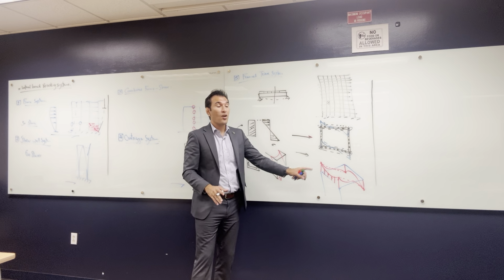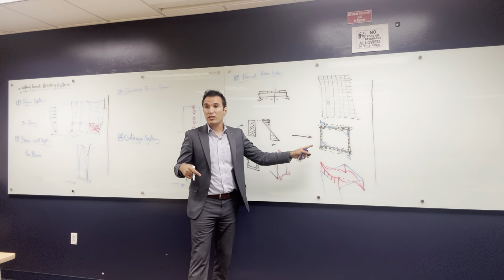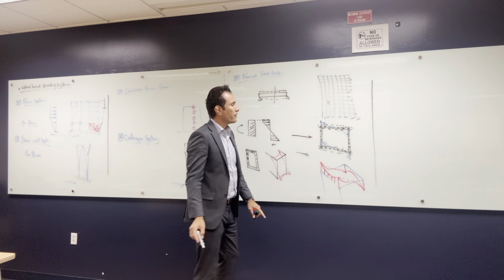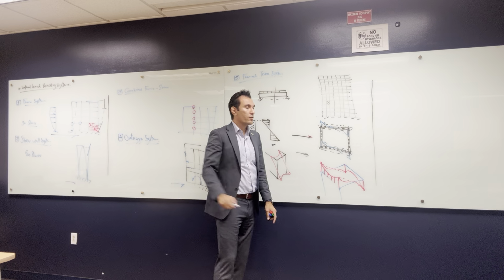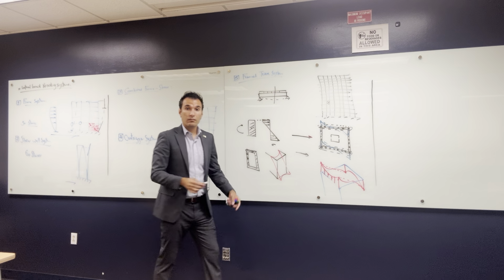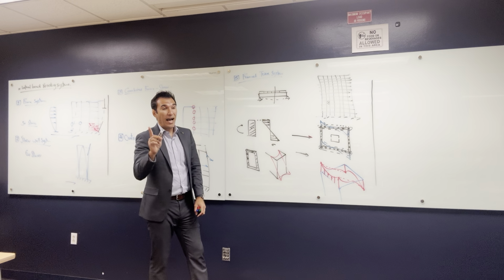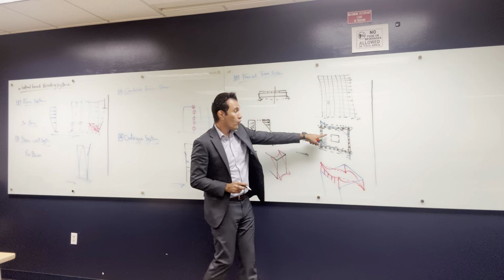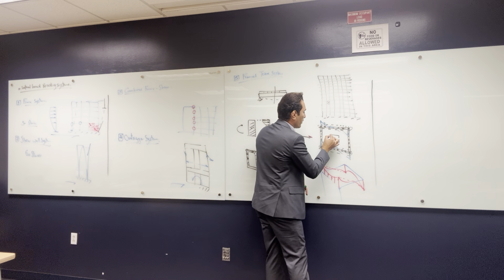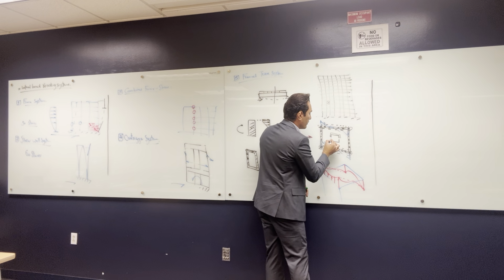So sometimes we have to use other systems with this system. For example, sometimes after putting in all the tube system and everything, there are still lots of forces. So I will end up using shear walls here in the middle. Like I have a core here and a core here, and I use it, and it's going to be something like this.